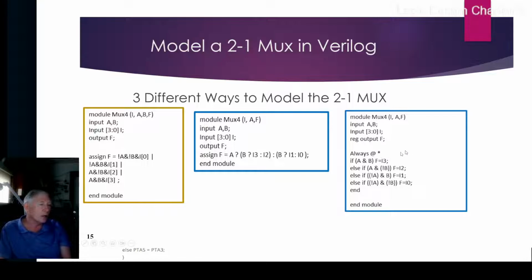But Verilog allows you to misuse it for combinational design. And the synthesizer is smart enough to realize that we were just kidding, and it's going to resolve it back to a combinational design, even though we're using a sequential design construct.